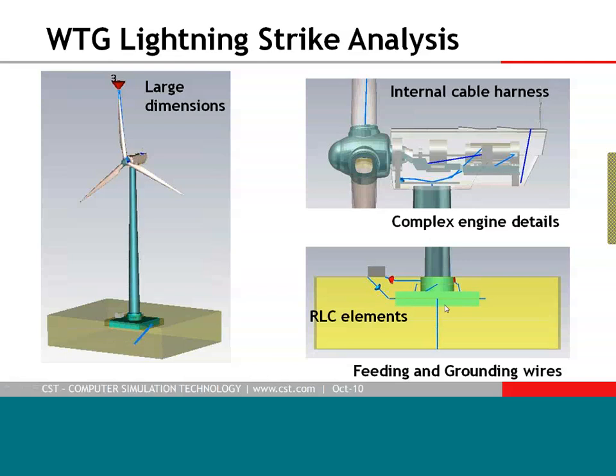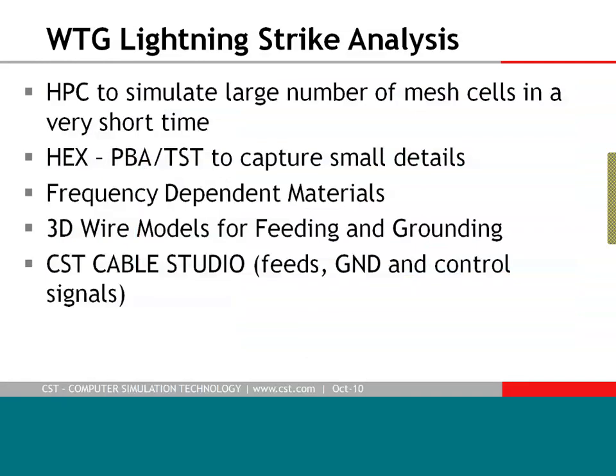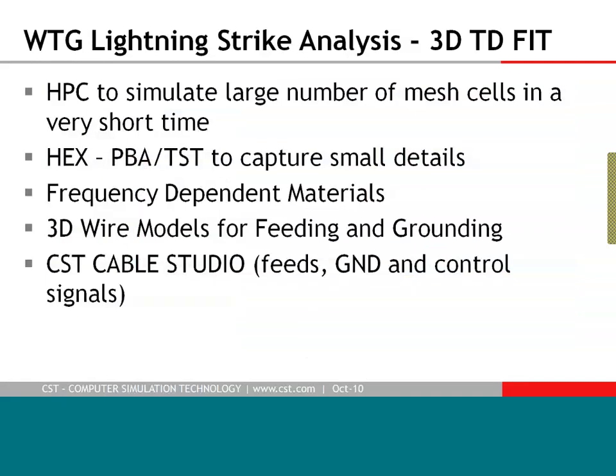modeled. And don't forget that we have to describe all the feedings and all the grounding lines, which can be easily done by wires. What are the features that we use for that? All the simulations I have performed on this wind turbine generator were done by the transient solver, based on the finite integration technique.